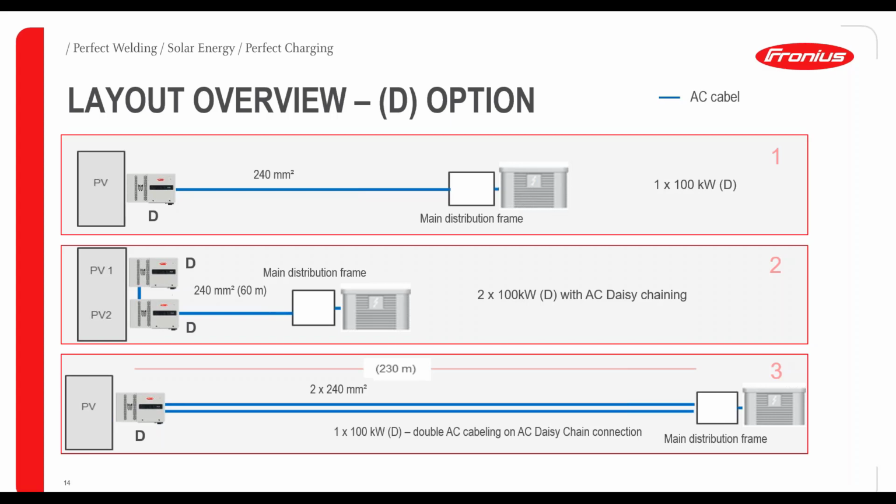Perfectly fine here. Second, down below, we would have an AC-DC chaining option. Again, 240 square millimeters would be used here. Also a perfect option here. And because of the big AC cable diameter, we don't have so many losses also. Cable losses are also very important in these equations. And here it's not that big of a problem because of the big diameter, cross section, sorry.